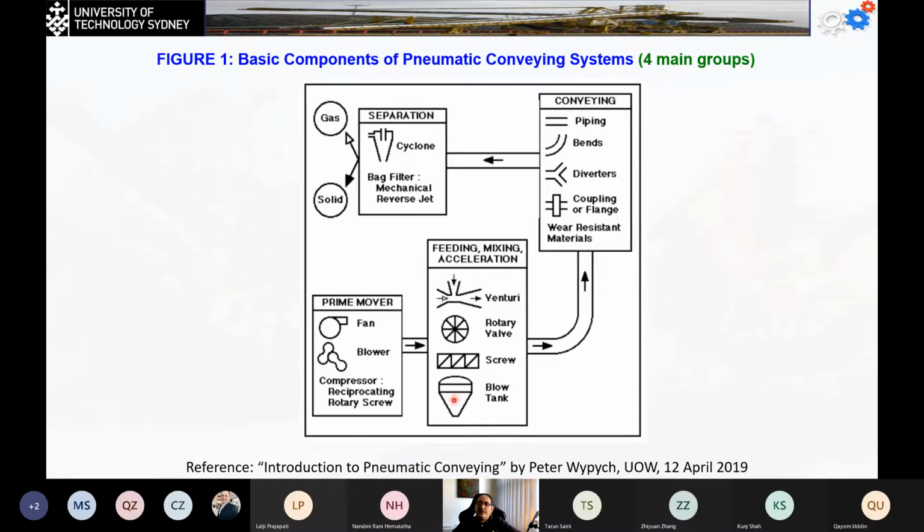Now, why do we need this equipment? Otherwise, the pipe is going to be pressurized and push the material up, unless we use some of the feeding equipment. In this case, the velocity here is going to be much higher than the velocity of the air at that point because of the venturi effect, and thus we prevent the air from blowing the material upward. Instead, they are mixed and go through the outlet.